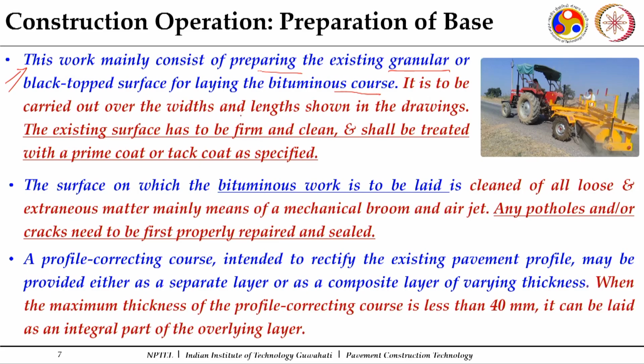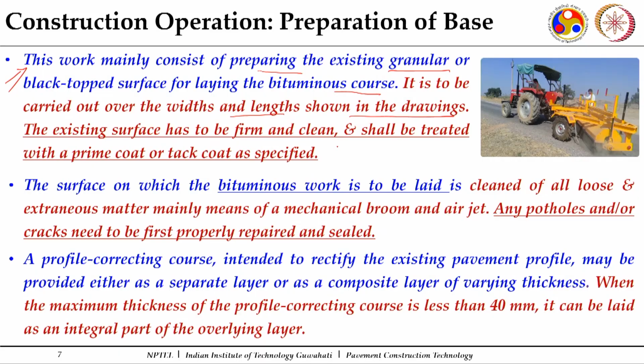It is to be carried out over the width and lengths shown in the drawings. So, whatever width is to be prepared, as per the drawings which are available, that surface or that base has to be prepared up to those particular widths. The existing surface should be firm and clean. There should be no depressions, undulations or foreign material present on the surface, and it shall be treated with a prime coat in case of granular courses, or with a tack coat as specified. So, this will be already specified.